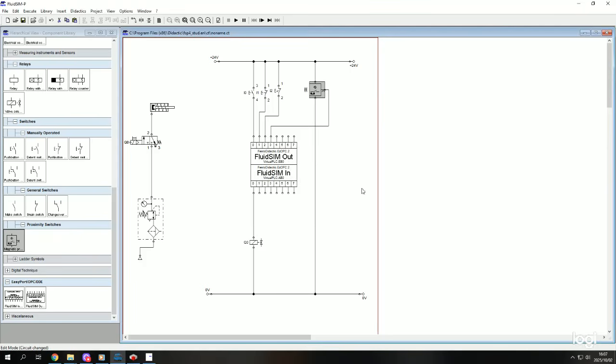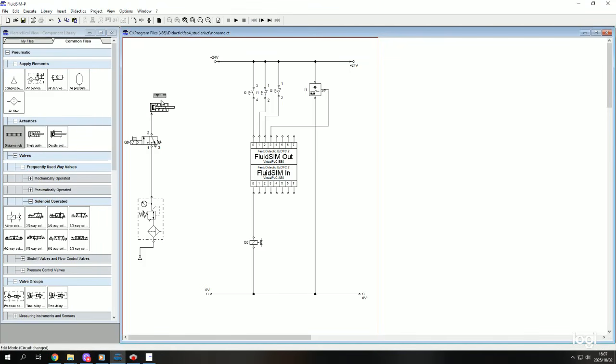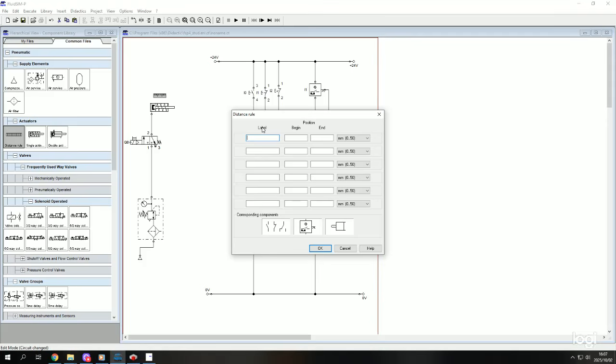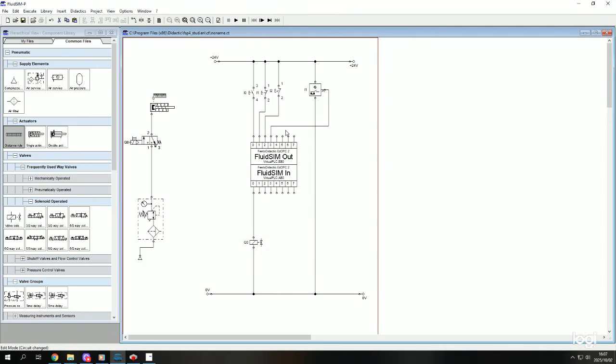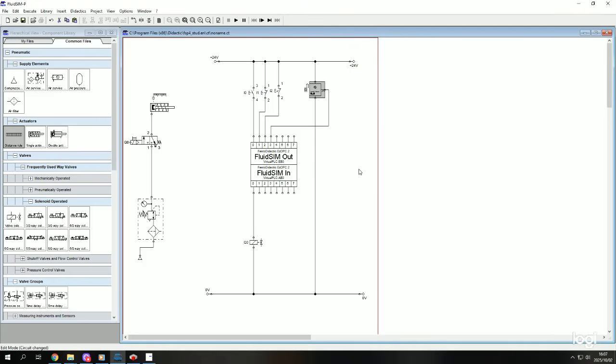So we are introducing a double acting, okay, no, we are still on a single acting cylinder. We need a ruler because we have a sensor to define our position, which will say it's I3. It must define position 0 to 0, which is the rear end position, our I3. This is our I3. Okay, so this arrow shows that already the position has been detected, which is the rear end position.